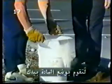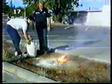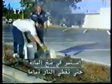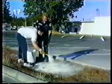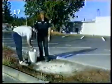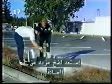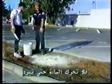To be ready for immediate and effective use, portable fire extinguishers are inspected and maintained. The three important factors that determine the potential effectiveness of a fire extinguisher are, first, accessibility, second, serviceability, and third, ability to operate. Determine accessibility by checking that the extinguisher is in the correct location and that it is easily accessible. Check to see if you can easily read the operating instructions on the extinguisher faceplate.